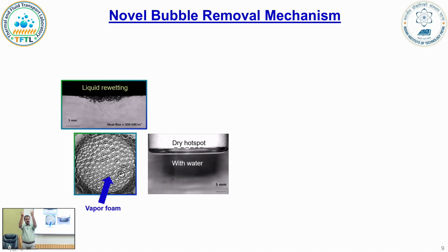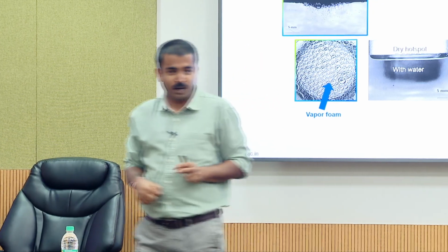That's interesting, but what is more interesting is, this is how you see them from the bottom. These bubbles are coming up against the gravity, coming down against the gravity. If you just do a force balance, buoyancy on any of these bubbles is acting up. Surface tension, because it's an inverted heater, is also pulling them up. So what's pushing them down? Because if we can push them down, we have basically compensated for the gravity, and anything like this can be very useful for zero gravity applications.